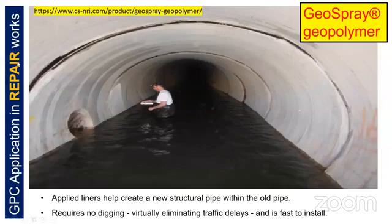Now, repair material. Earlier, we discussed geopolymer concrete as a repair material in pavement. Now, you can see here one of the geo-spray type of geopolymer. That means it is a spray material. It can be applied as a liner, and it helps in creating a new structural pipe within the old one. Where cement concrete pipes are there and repair is very difficult, you can use these types of commercially available products based on geopolymer. It requires no digging, and that means you can eliminate traffic disruption daily.